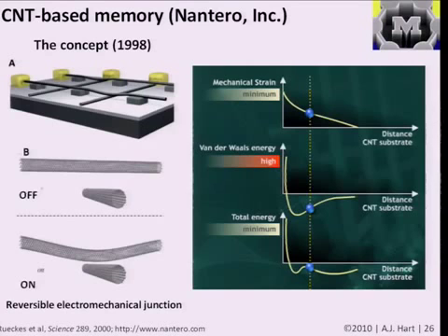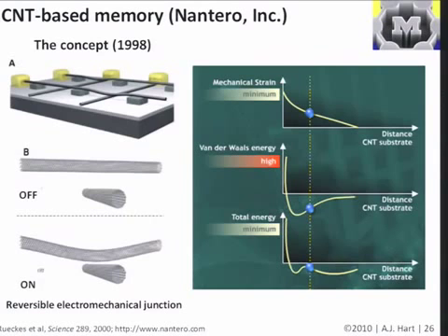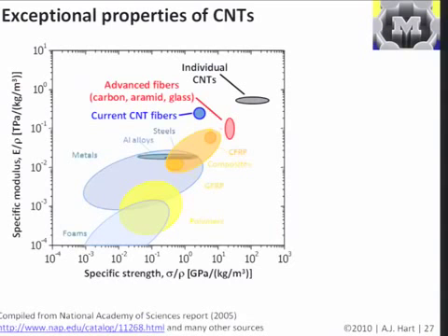But their process is integrated in a bunch of clean rooms, and they're also one of the companies driving the development of a lot of the standards for incorporating nanomaterials in semiconductor manufacturing, because they are trying to make products that do this. There's also a company that Nantero has worked with called Brewer Science that sells commercial dispersions of nanotubes that can be spin-coated like a photoresist. It's quite an expensive thing, but folks who want to try to do photolithography on a nanotube layer can buy this well-engineered and characterized dispersion, this kind of nanotube ink, and take it into the clean room, like you could take it into LNF here, and use it kind of like a photoresist and process it as a layer. That has come out of their many years of development toward this eventual concept. So even though their first concept couldn't be made, they've pushed forward and ended up with something that is a compromise between their science dream and the practicality of the specific technology that they're making.